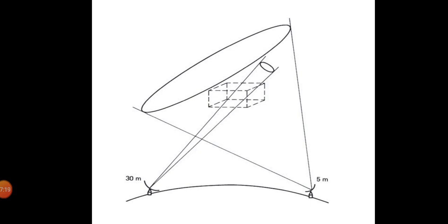If, for the sake of argument, this is taken as 36,000 km, the total variation in the height is 72 km. A C-band satellite can therefore be anywhere within the box bound by this height, and the plus or minus 0.1 degree tolerance on latitude and longitude.